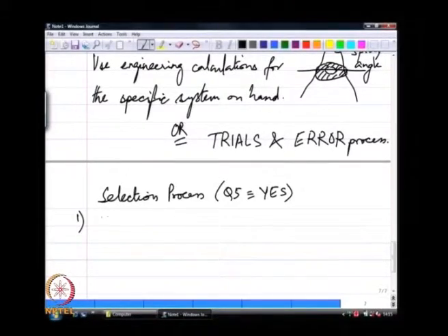Okay. So, essentially if you looked at the previous design process, we did not really get down to drop size in any way, because if I specify cone angle and flow number, I really have lost all the control over the drop size. I really do not have any other handles to control drop size at that level. Whereas, with air assist atomizers, I have another independent control over drop size. Okay. So, this is where one would need some more information about drop sizes.